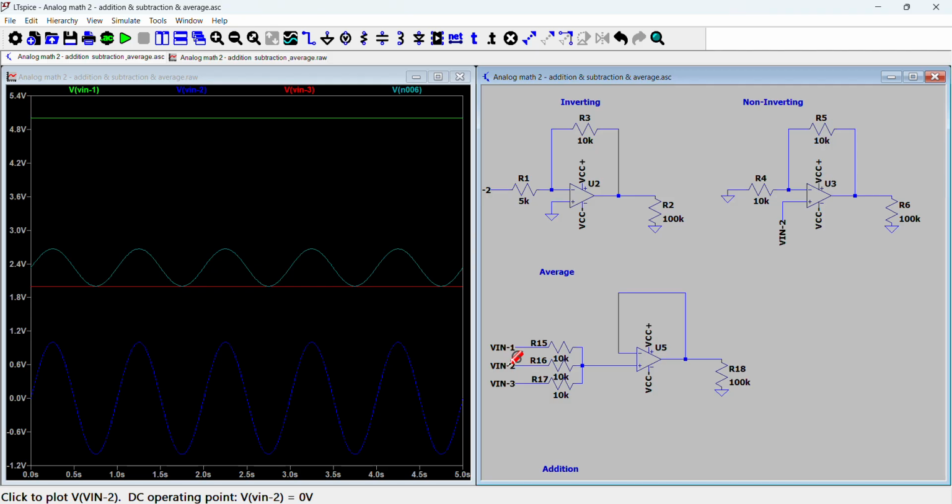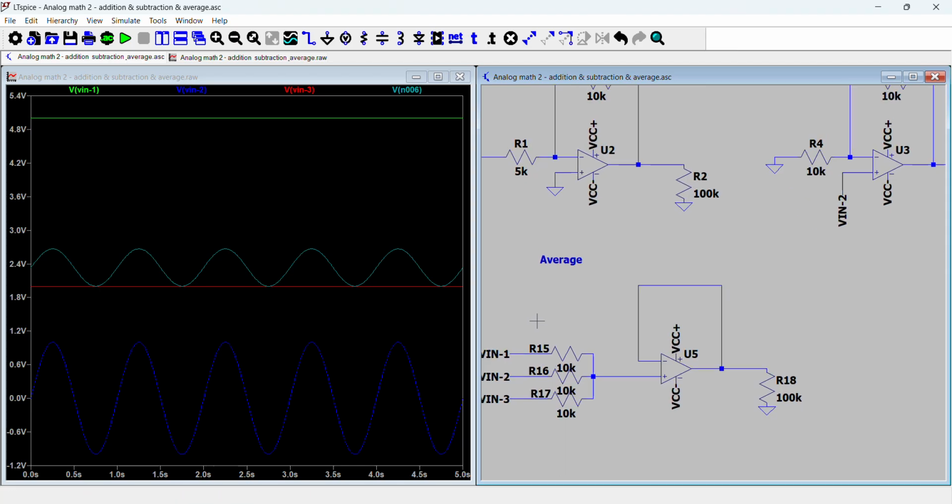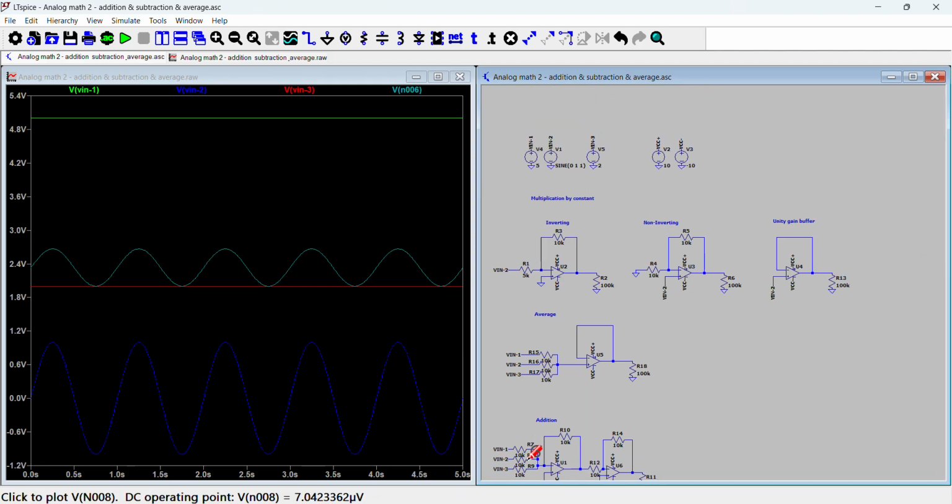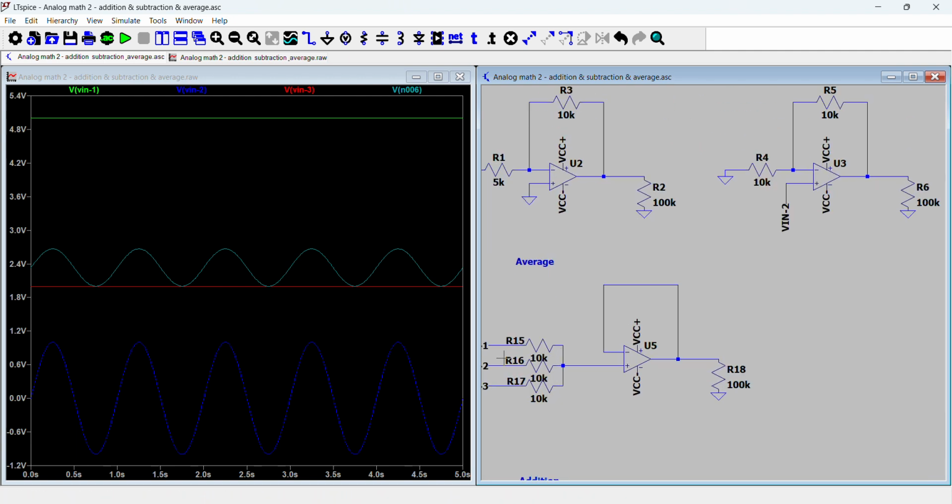If you had a diode, for example, or a PN junction of any kind, on the output of this voltage supply, sometimes you can't actually sink current, and in that case you have to use an addition circuit, a weighted addition circuit, which I'll go over later, in order to create the average.